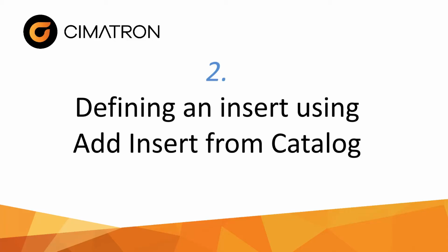Once the mold design is farther along, it becomes a lot easier to see geometry in the cavities that would be better designed as an insert, either to make manufacturing easier or provide a vent or some other reason. So let's now look at the specialized tools that Cimatron developed just for inserts. The first one to look at is adding and cutting an insert from catalog.